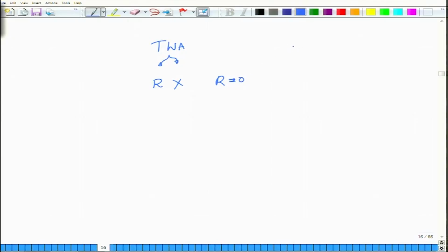So what you would actually have is a range of values of R, say from the ideal 0 value to about 0.1, let us say, wherein we would treat the semiconductor optical amplifier as a travelling wave amplifier, and beyond that we would treat them as a Fabry-Perot amplifier. Okay, so beyond the value of R of say 0.1, 0.12, 0.15, you would deal with them as a Fabry-Perot amplifier.